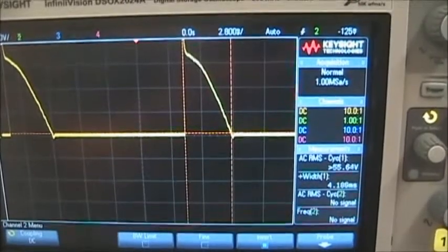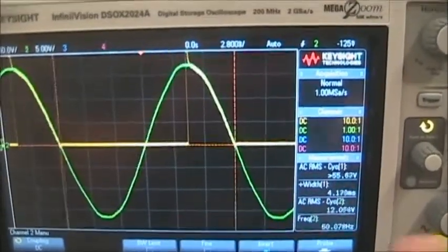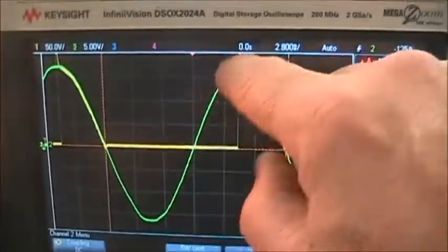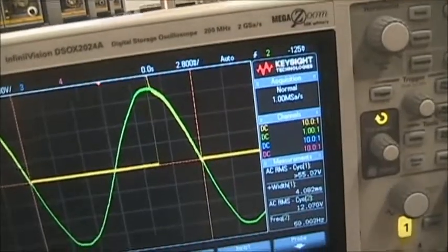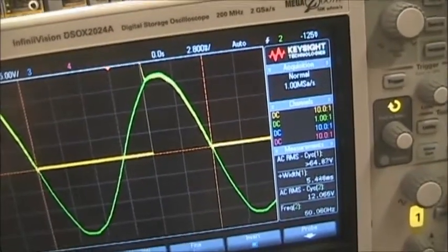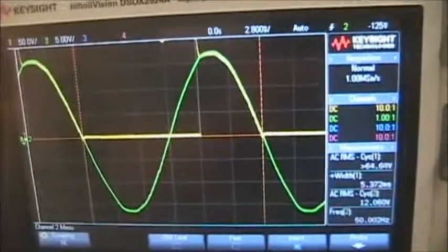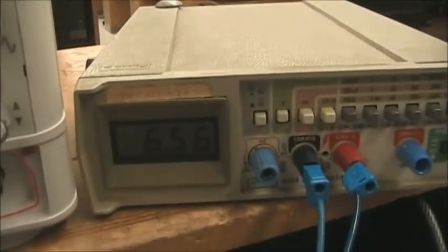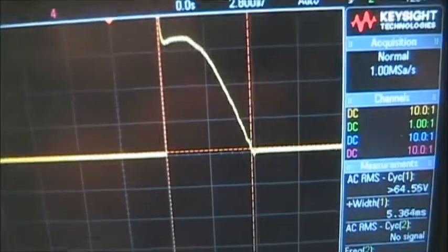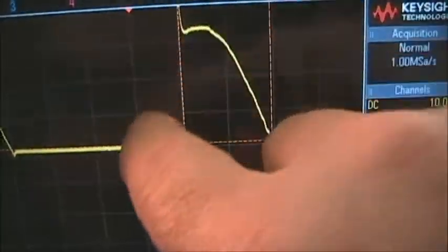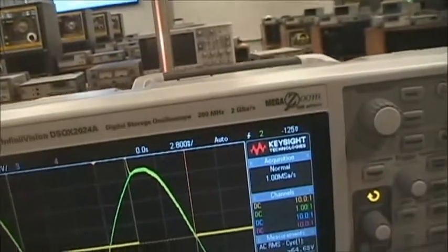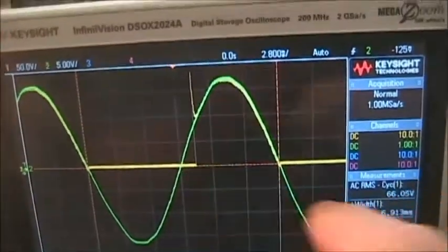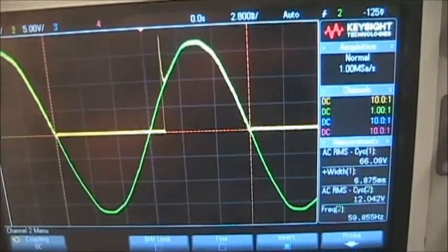We've got about half of the signal. Remember, that's the lamp signal, and the SCR is taking the remaining portion that adds up to the green. So I'll increase it now to 60 degrees of signal measurement. We're now at 65.6 volts RMS, and the voltage across the SCR is the remaining part of the signal plus the reverse. And then finally we'll do a little bit more, maybe halfway to the 180 degrees from where we were.